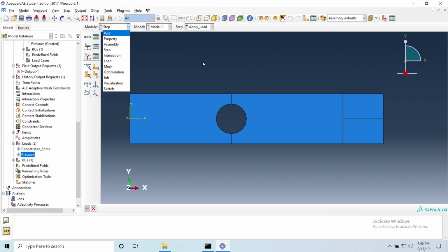If you request energies or contact or fractured energies, then you need a history output request, but we don't need those for this example. Because in history output, if you have a nonlinear behavior, then you ask for every time increment and for every element and for every node this output quantity. So it becomes very... So doesn't field output do that? Yes, it does do that. But we are in a linear increment, so it's going to be only computed at the end of the linear increment.